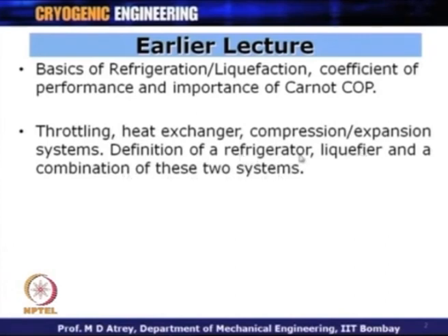We talked that refrigeration is normally a closed cycle process, that means the working fluid never leaves the cycle, while a liquefier can be called an open cycle process because the working fluid itself gets liquefied, and whatever liquid we collect, the same amount of gas has to be added to counter the deficit.